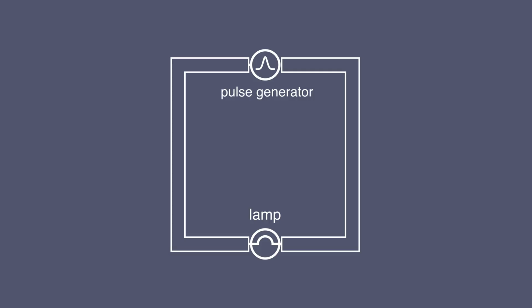In the case of our toy circuit, the current here will be paired up with the so-called return current here. I use the term return current because that's what it's usually called, but it's a bit misleading because it suggests that the current has gone all the way around the circuit to get here, which is not really true.